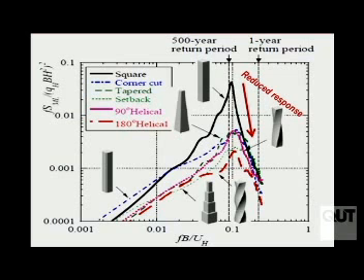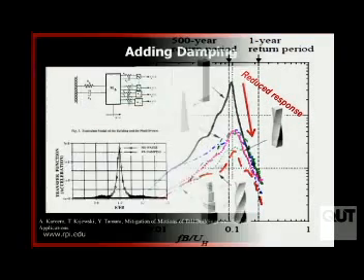So that opportunity for resonance disappears, and we can now have a much less severe condition for our structural response, our human perception of motion response, by changing the shape of the structure. And here you can see the square rectangular shape, the black line, giving this really large response at the resonant frequency or the Strouhal number. By tapering, by twisting, by stepping, by cutting the corners, you can generate more or less the same amount of reduction in response. Okay, so you can change the response quite dramatically in that sense, and this is an order of magnitude, so it's fairly important.